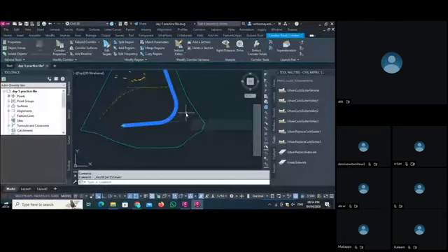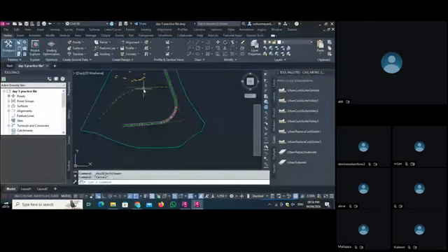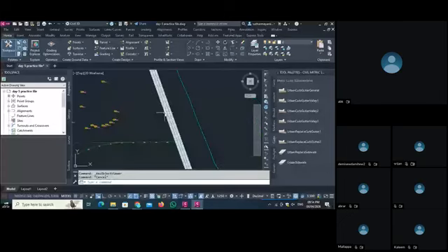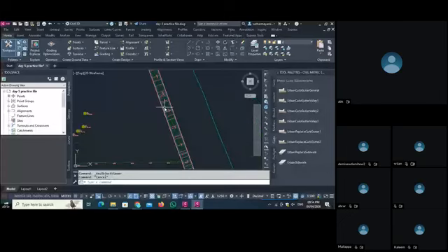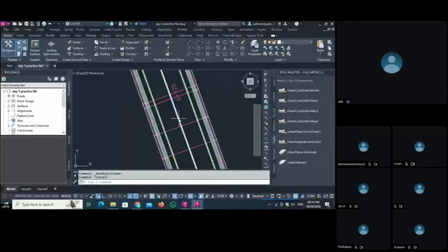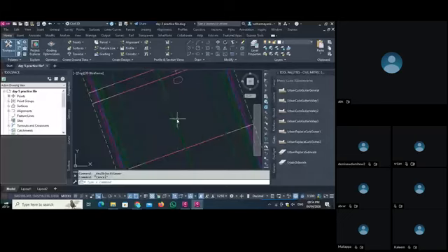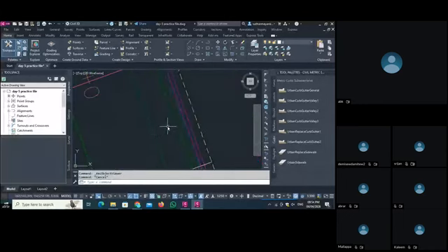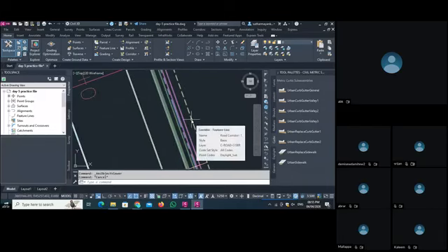So what we do now, see, intentionally I didn't give a daylight here. Right now our road has no target. So you see this is our center line of alignment. This is our road length 3 meter. This is our shoulder 1 meter. Then we set a curve here, and if I click here, it will show the